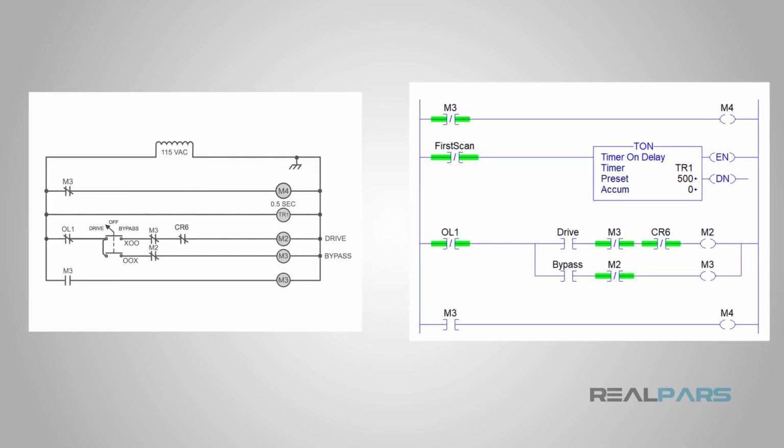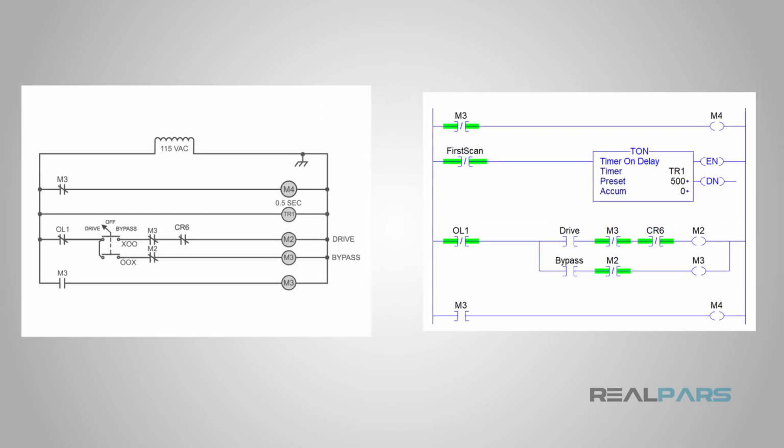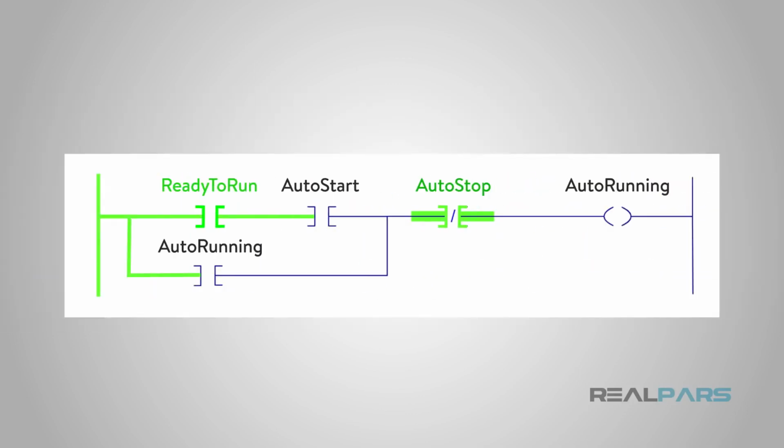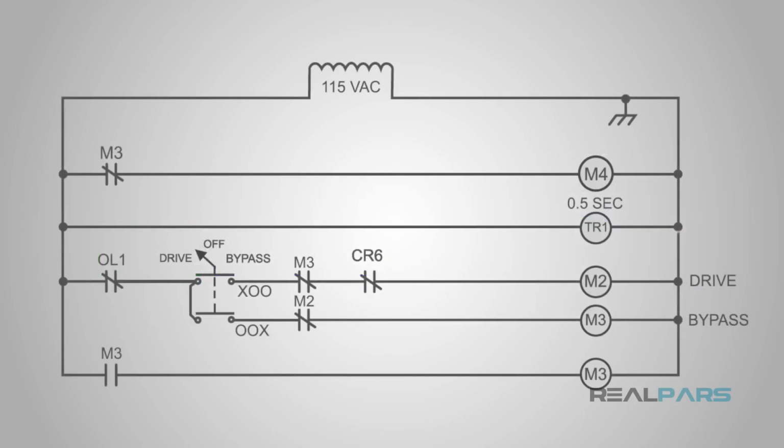The circuit we just drew in ladder logic, and the one that we could have drawn on paper, is in thousands of motor starter panels all over the world. They add stuff to it, but the basic circuit and meaning are the same. Push the start button, the motor runs, until you push the stop button. Welcome to real-world ladder logic.